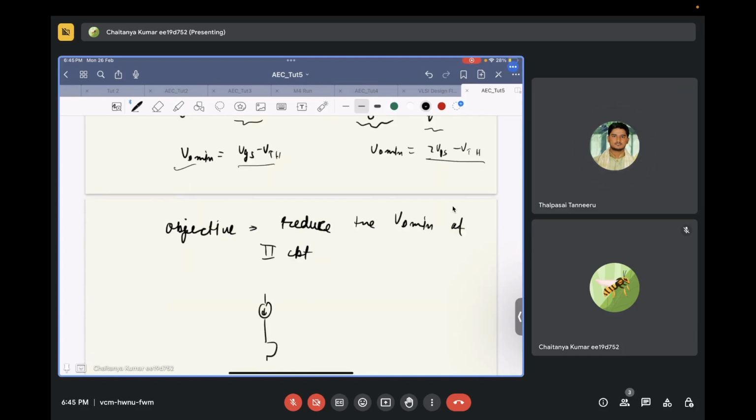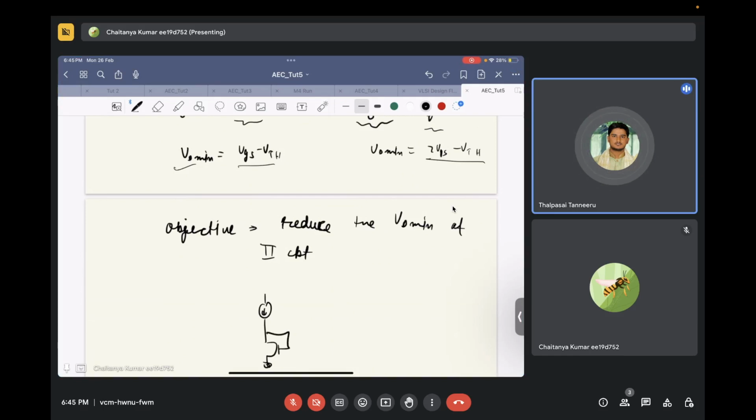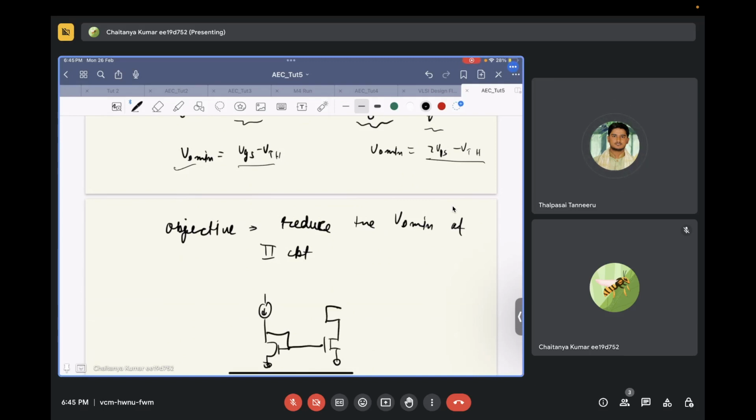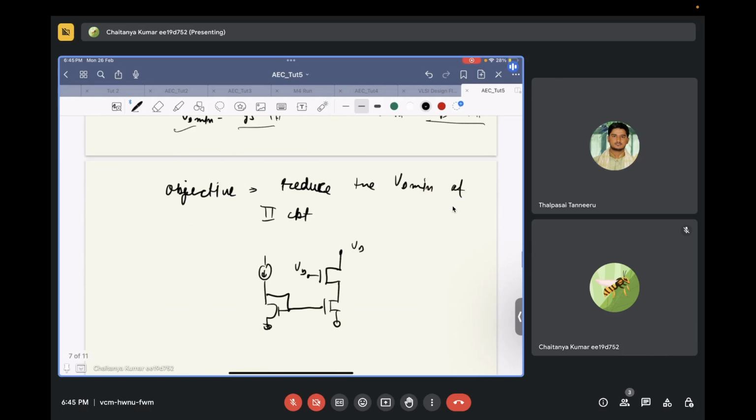Now this value is VB, this value is VD. So how low can you take this VB? The nominal current from this transistor is still alpha ID. This transistor still has its ID. Now this particular voltage is VGS, and the voltage developed across the upper transistor will still be VGS.